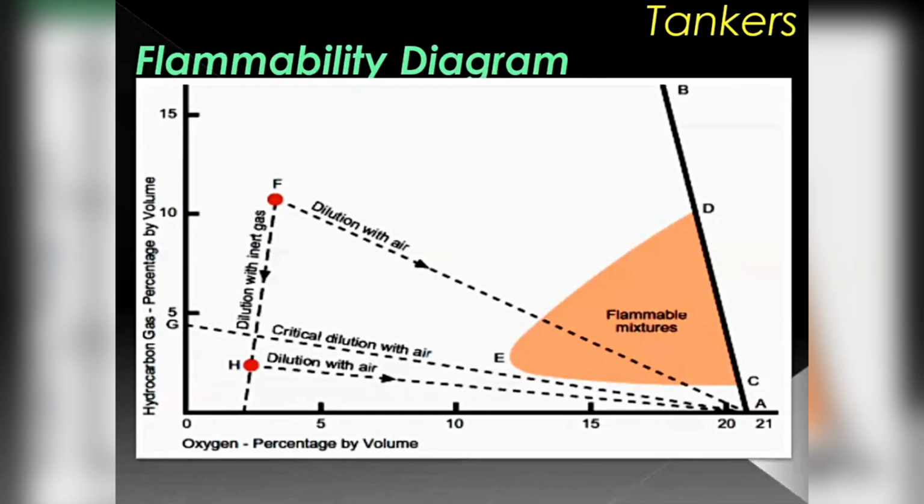No, then it becomes an open gas. You're doing the tank cleaning in the open atmosphere. It should be a closed system. Second, you are disturbing the sludge, and hydrocarbons are heavier than air. They stay at the bottom. You understand? And it gets mixed up when you disturb it. This sludge is emitting hydrocarbon vapors. And if you have the right mixture inside the tank, and a static current is already flowing, you will have a fire first, and then you have an explosion. That is why it is required.